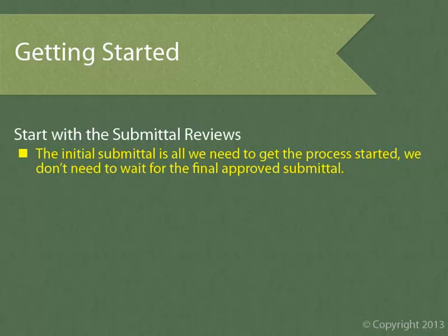Unless you have a really easy project, exterior skin coordination is going to take a lot longer than a couple weeks, and we need the coordination effort complete before releasing materials for fabrication. Don't wait. As soon as the exterior skin related submittals start rolling in the door, get the exterior skin coordination process rolling. Time is of the essence, because the exterior skin is virtually always on the project's critical path.